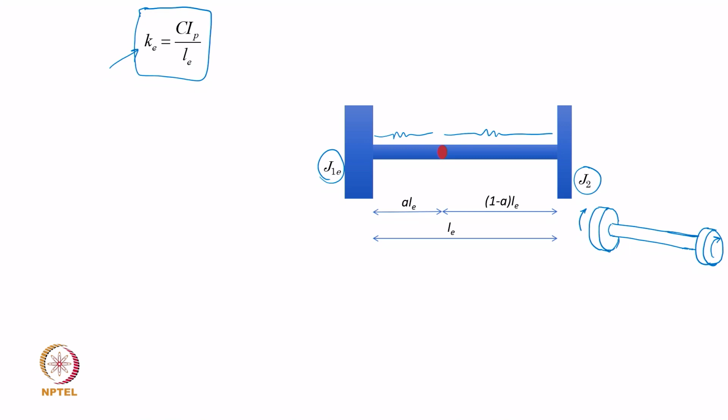In the second natural frequency, these 2 inertias move in opposite direction. So, in this particular case, the motion now is going to be this mass moving in the counterclockwise sense and this one in the clockwise sense. So, there is now going to be a twist and strain in the shaft. So, this shaft is going to be under torsional strain, shear strain, and then this disc is going to move counterclockwise when this is going to move clockwise, and after some time they will flip their direction. So, they will keep on oscillating like this.